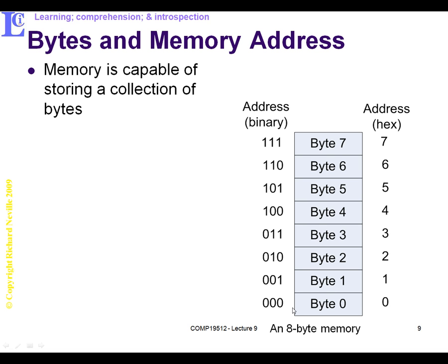So what we're looking at here is the memory capability given specific information. One, given an address line width of 3 bits, it will address only 8 different locations. Okay? So each of these bytes, if we put on an address bus 100, we'll specifically be addressing byte 4 in the 8-byte memory.